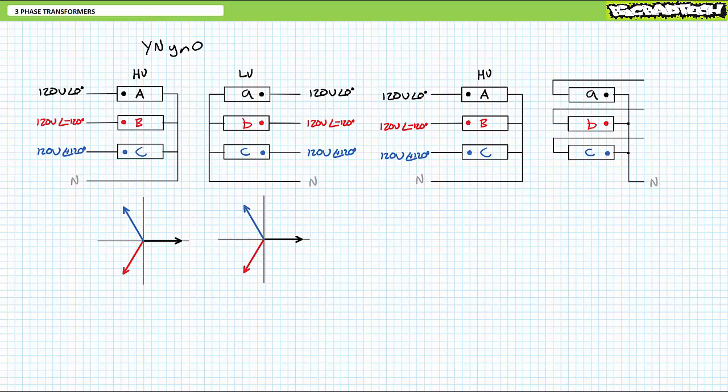Used in this fashion, the low-voltage secondary outputs of each transformer will be perfectly out of phase with the high-voltage primary inputs, or exhibit a respective plus or minus 180-degree phase shift. When the input peaks, the outputs valley. When the inputs valley, the outputs peak. Long story short, if you're using the secondary backwards, add or subtract 180 degrees from each phase.